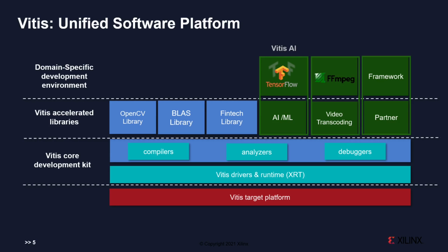You can leverage integration with high-level frameworks developed in C, C++, or Python using accelerated libraries, or use RTL-based accelerators and low-level runtime APIs for more fine-grained control over the implementation. Basically, you can choose the level of abstraction you need. Drivers are also provided alongside runtime APIs, and as a developer, you target a pre-customized platform that comes with predefined hardware ready to communicate with the runtime drivers, as well as customized lower IPs to connect to the platform.